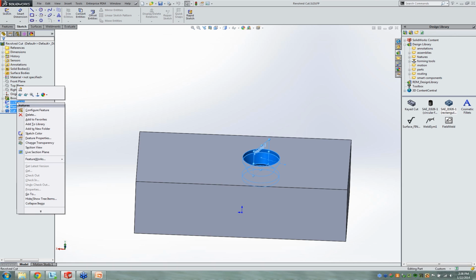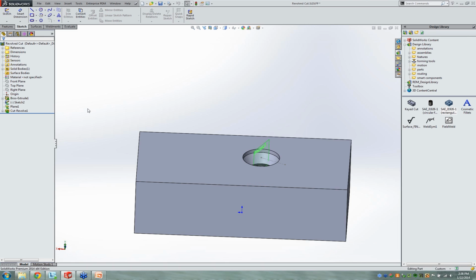And from a right click here, I have the ability to just add these to the library. And we can see what that does. It puts a little green L on top of them there. And it's saying those are the features that are actually in this library feature part. That's what we want to bring in, kind of ignore everything else.